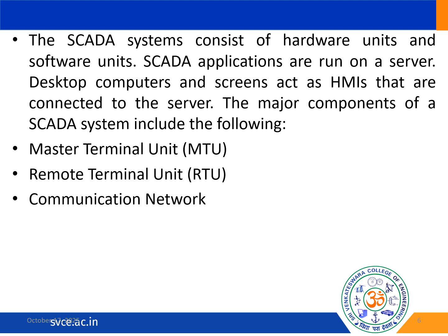There are some primary components of a SCADA system, which include the master terminal unit, called the MTU. It acts as a central controller, coordinating data flow and command execution across the system. That's about the master terminal unit. Next we'll be learning about the remote terminal unit, that is the RTU. Here it interfaces with field equipment to collect sensor data and it can execute control commands.